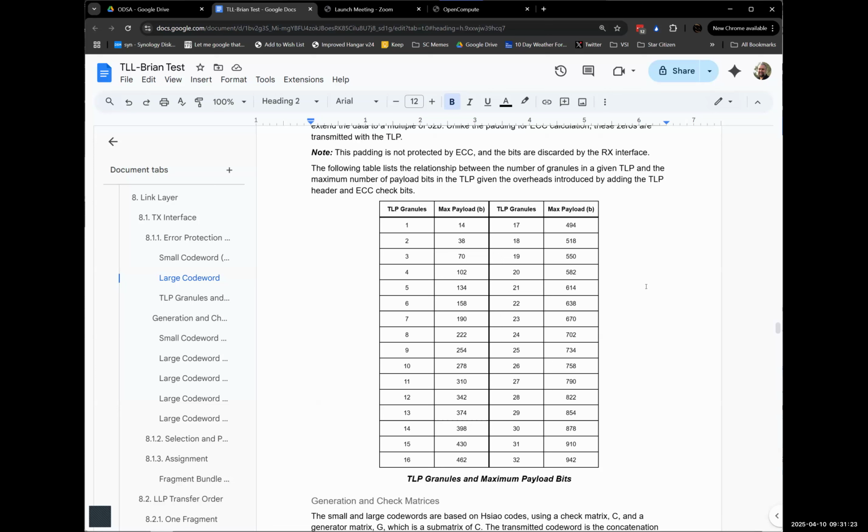And so all the bus protocol variants, at least the ones that David and I worked on, we worked on a spreadsheet, and he gave me a version of this chart, and we did a little Excel magic and picked bus protocol variant options, like AMBA bus widths and things like that, that gave us a reasonable utilization of the payload for the given LOP size that we have.